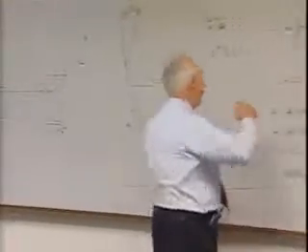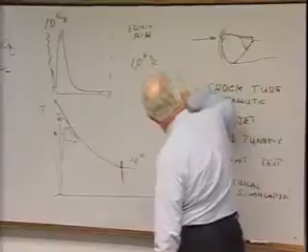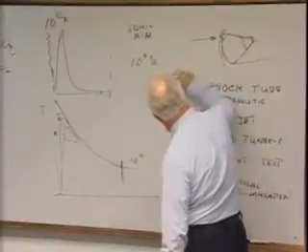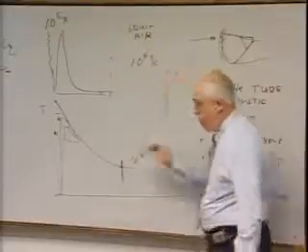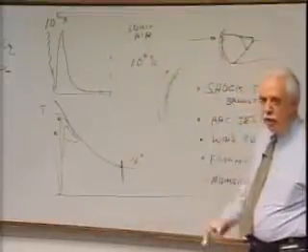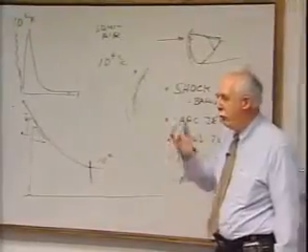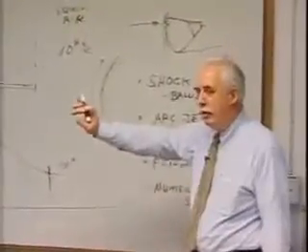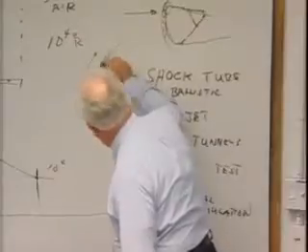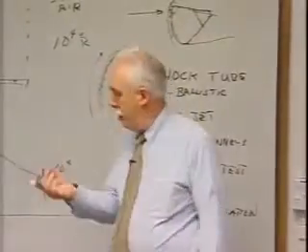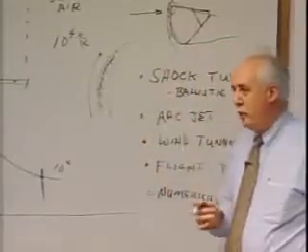If I blow that up a little bit, I've got a surface here of ablator, which is pyrolyzing and charring, and I've got a flow over the vehicle. I've got one heck of a pressure gradient. And I just described this char. It's a nice porous carbon like a charcoal briquette. If you blow on a charcoal briquette, you can blow your air right through it, and it flames up. That's exactly what happened here. We had flow through. The honeycomb wasn't as high temperature as the carbon, okay? That was just there to hold it as a system degraded.